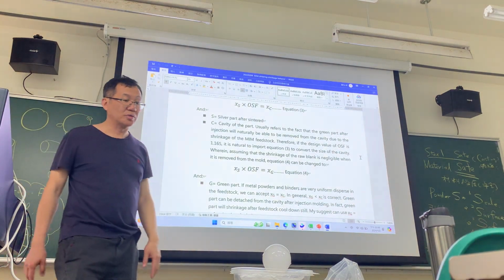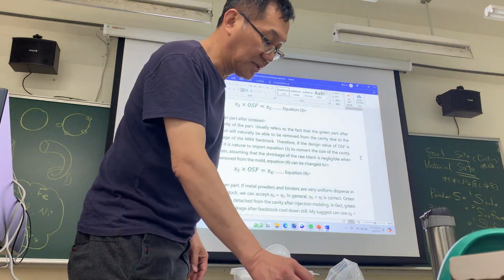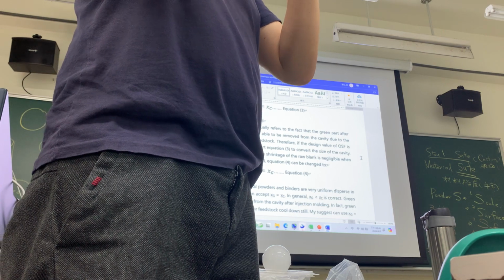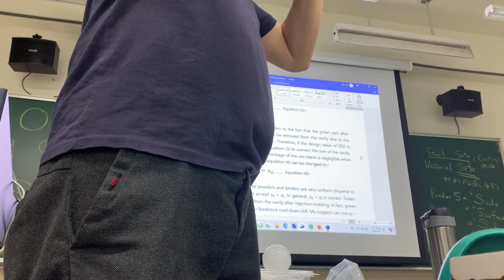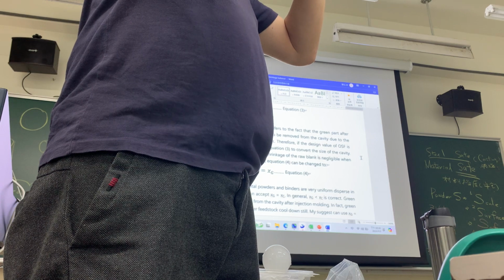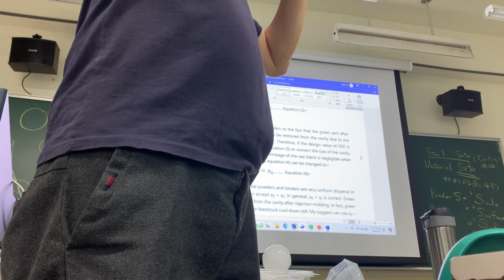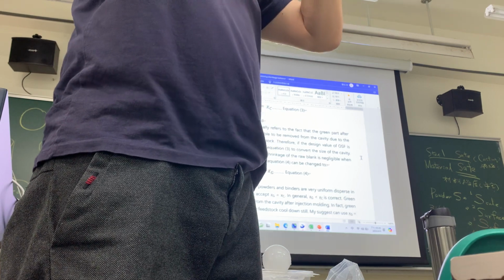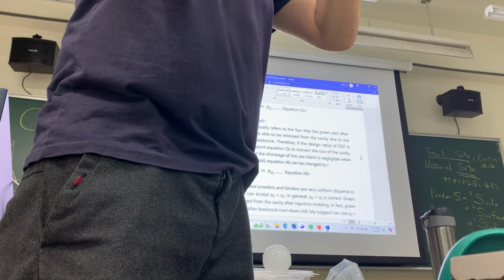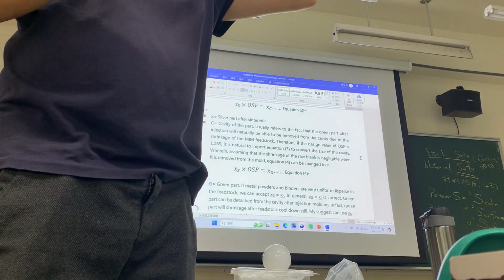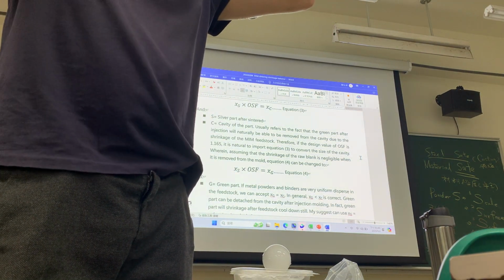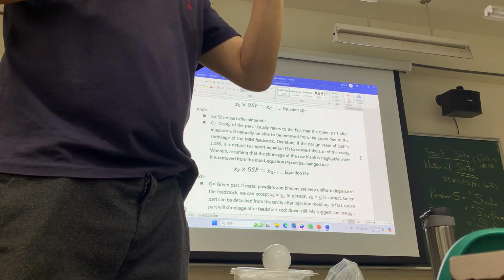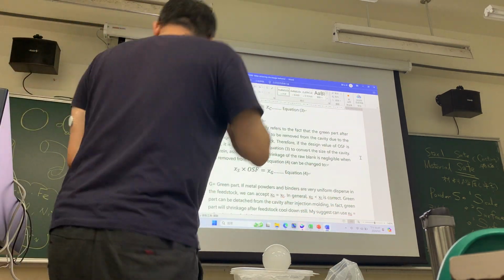Yes, it's true, because we want injection molding. You remember this molding? I just said we use injection molding with very high pressure. The high pressure lets more material go inside, then it cools down. After cooling down, it will shrink. If there were no shrinkage, you cannot release from the tooling cavity. Am I right? Yes, you cannot release. So remember.